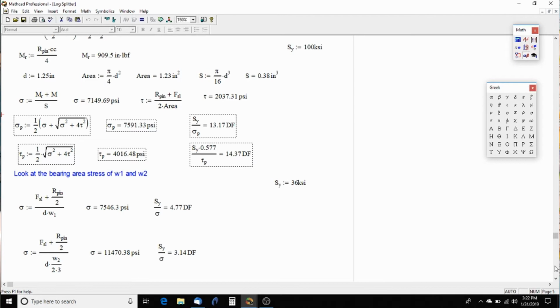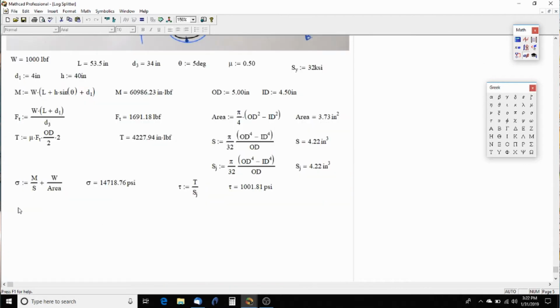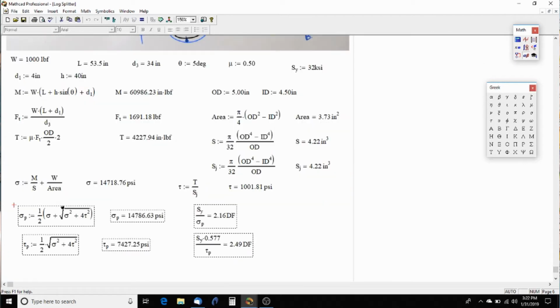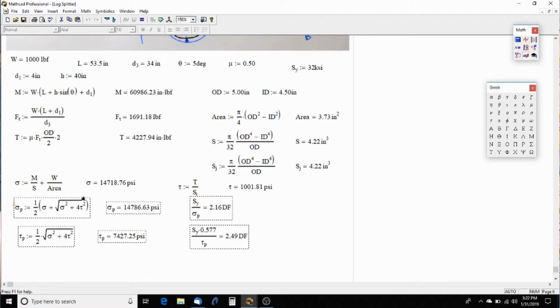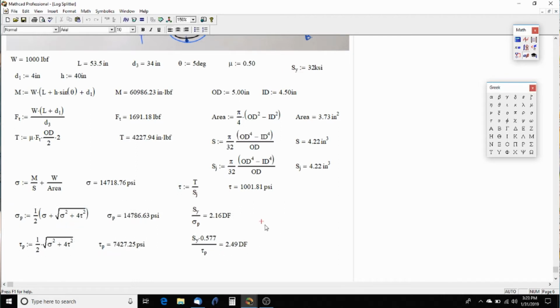I highly suggest, if you haven't seen it yet, look at the Mohr circle video and figure out where all this comes from. And you can see, wow, we got a little problem here. I always love to have a design factor of 3, especially on things where I don't know what they're made of and don't know what they're necessarily doing. Have the safety factor of 3. And you can see here our safety factor is 2.16.